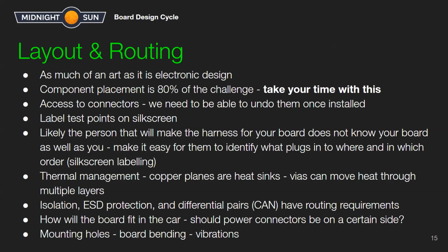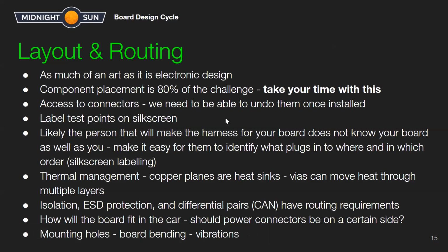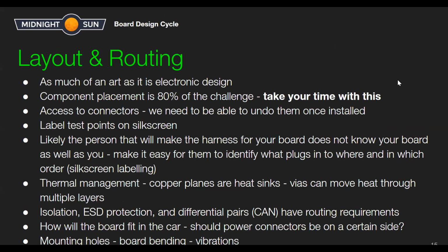So one thing to keep in mind is that connectors, when you're removing them and putting them in, you need to have access to get your finger around and to press the tab. All connectors have a positive locking element that we need to push down. So we'll put two connectors right beside each other with that tab facing each other, and that's probably common sense. It's good to mention again.